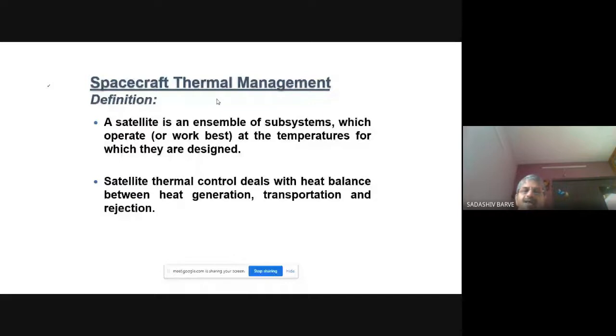As the temperature of that package keeps rising beyond a certain range, its dissipation starts rising, the efficiency of those components comes down, and that particular package fails at an early stage. That is why, package by package, we need to maintain a limited temperature range.